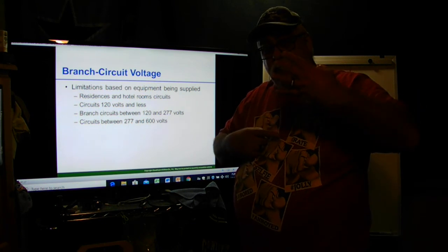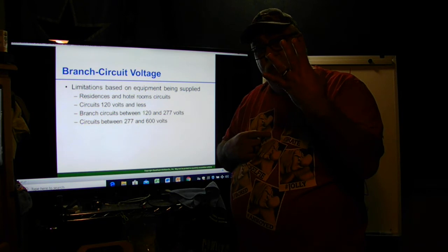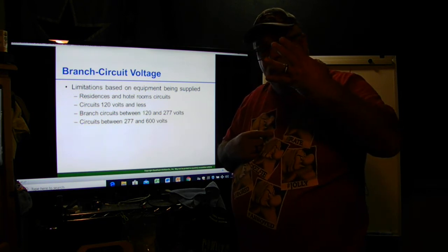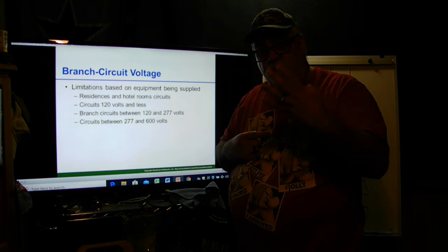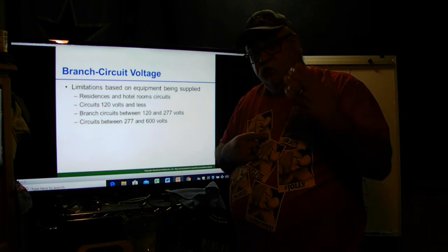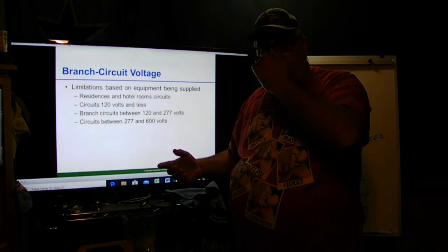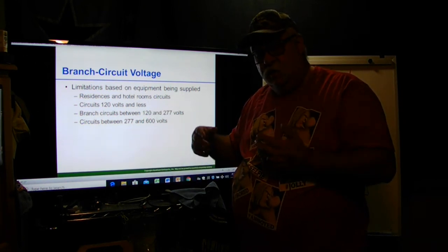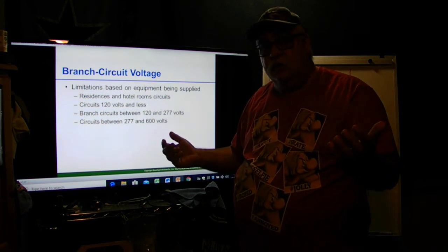So here I got a 15 amp breaker. I can only put 3 lights. Or a 20 amp circuit, I can put 4 lights. If I got 4 amps per circuit, I can't put more than 4 on the circuit. Okay, 4 amps, 4 amps, 4 amps. That's 16, almost 16. So 16 times 80 percent because it's on more than 3 hours. It's lighting, so it's a continuous duty. So I can't have more than 16 amps.